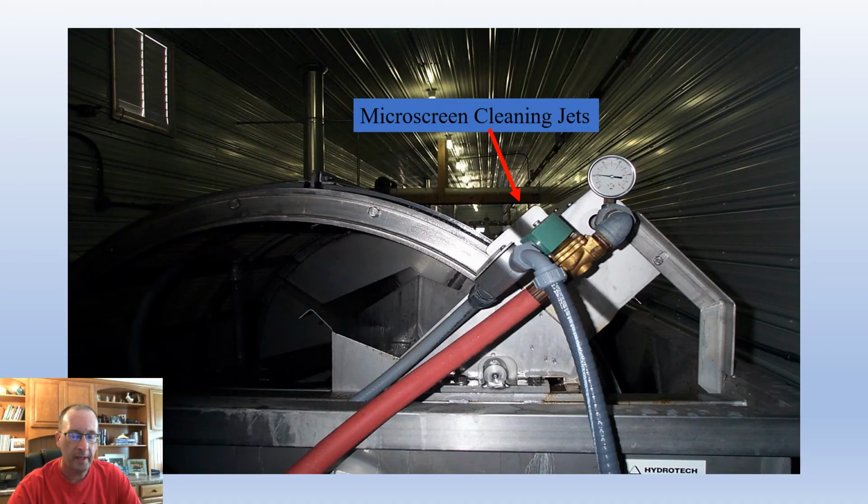When the unit finally needs to be cleaned, or I would dare say backwashed, the rotating screen becomes so impregnated with dirt that the water level inside the tank where the drum sits actually starts to rise. And eventually that turns on a special float valve that activates this spray bar.